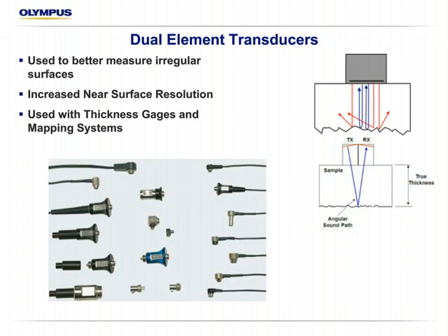You know, thickness gauges and other instrumentation will have algorithms to correct for that small V path as if it was 0, so we actually get a very accurate thickness measurement even by using a slight angle. So usually what we end up getting, besides a better chance of actually hitting and measuring the corrosion, is we get better near-surface resolution as well.